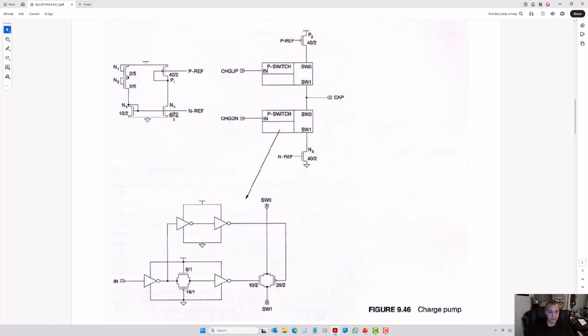So it's a different meaning: the numbers that we see when they are by transistors is different than the number that we see when they are by the gates. For gates it's about N and P. Here is width and length of the channel in terms of the minimum width, which is of the poly, which is 150 nanometers. So those are the circuits.